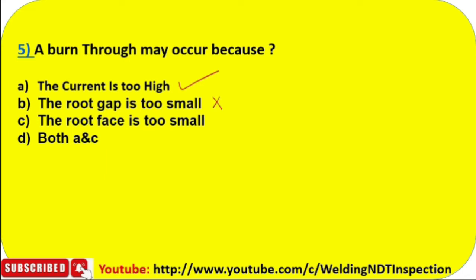The root face is too small: if the root face is too small, definitely this is your joint. You see here the root face is very small, so it will happen this way, and burn through may be generated in this area. That's why A and C are correct. So I think D, mentioning both A and C, will be the correct one. Let's see.